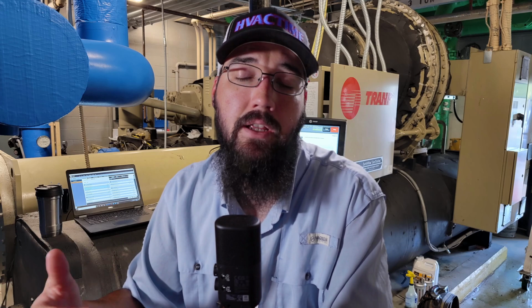So in a situation like that, sometimes that is the easiest solution. Just add some oil temporarily back to the system, let the recovery process happen the way it needs to, and then as you start running high oil levels again, start drawing that oil back off, so that you can return to a normal level and condition. You should know how much you added in, so you should know how much you need to take back out. Should be pretty straightforward.